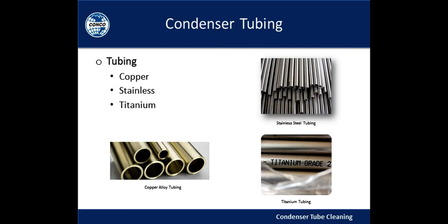For example, a copper alloy condenser tube will actually kill some microbiological growth. The presence of the copper kills the microorganisms. The biofilm is slowed down considerably. However, while it sacrifices itself to protect from the microbiological deposits, it forms an oxide, and this oxide grows like hair, and inasmuch it has to be removed from time to time because when it gets to a thickness, when it impedes the heat transfer, it's no longer working effectively to protect from corrosion.